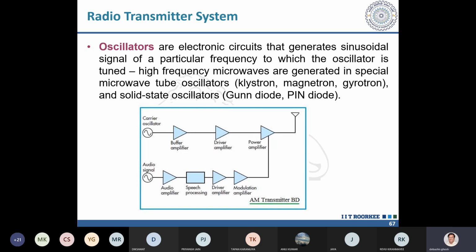Okay. However, for microwave range frequency generation, for satellite communication, you have to have the frequency translation to microwave range, gigahertz. Okay, microwave range is gigahertz, 10 to the power 9 of that order. For microwave, we cannot use the general oscillators, the Colpitts, Hartley, and all these oscillators which are made up of transistors, op-amp.